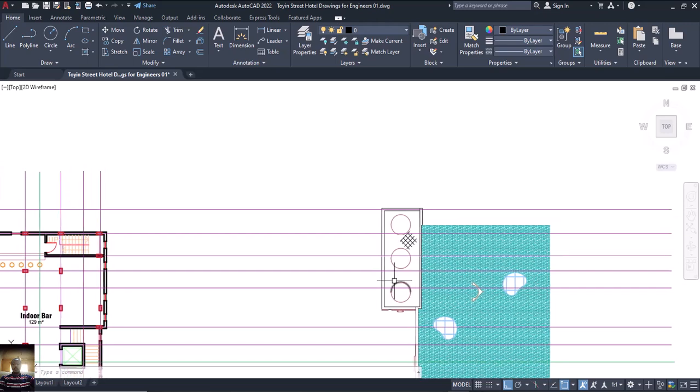If you do your conversion, 1,000 liters is equal to 9.81 kilonewton, but we are not using 9.81, we are now using 10, as it has been reviewed. So 1,000 liters is equal to 10 kilonewton. Therefore, if 1,000 liters equals 10 kilonewton, then 5,000 liters equals X.